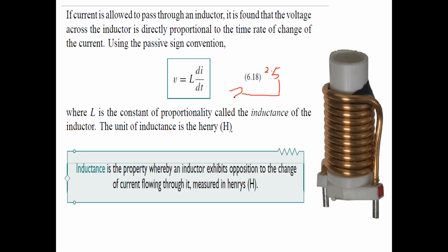This was the 2 milliampere line. Sorry, my drawing is not that good, but you have got the idea. So the slope of this jump line is infinity, hence the voltage of the inductor should be infinity as well, which is not practically possible.